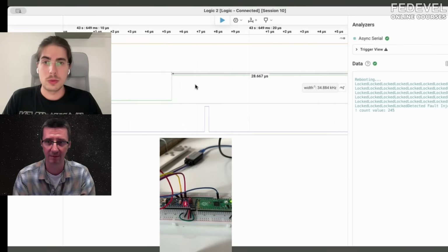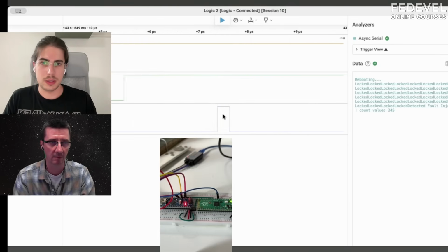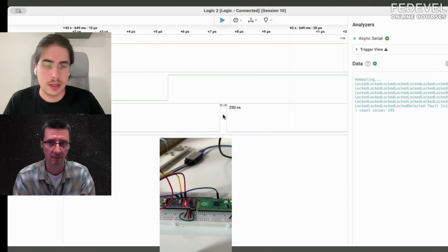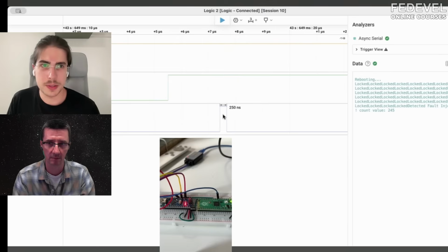Yes, definitely. What we see on most devices is a lot of crashes, because as soon as I do this too wide, the target will crash, and so I set some certain boundaries. But you can get a lot of crashes, especially if you affect registers which have important values. If you return early and you have stack canaries or software measures that are usually made for integrity, stability and safety, you can basically trigger them inadvertently, and then you can crash your target, and then you have to wait for it to reboot, and it takes a lot of time.